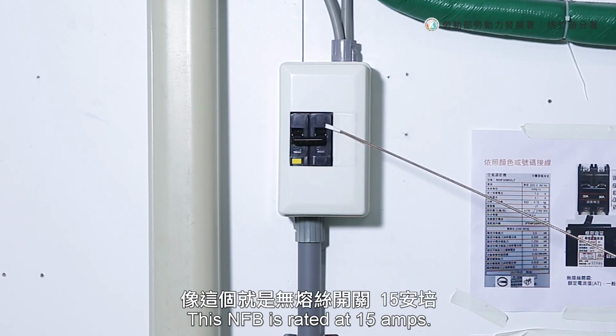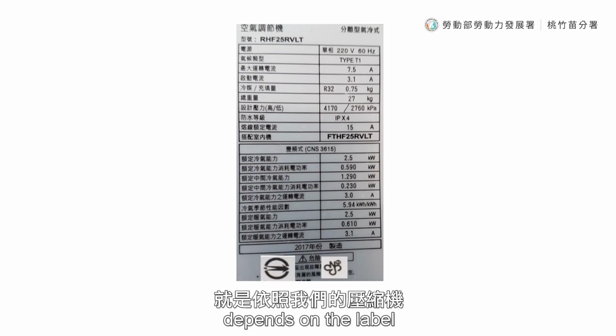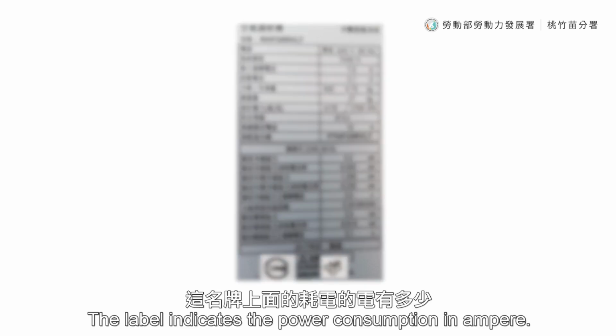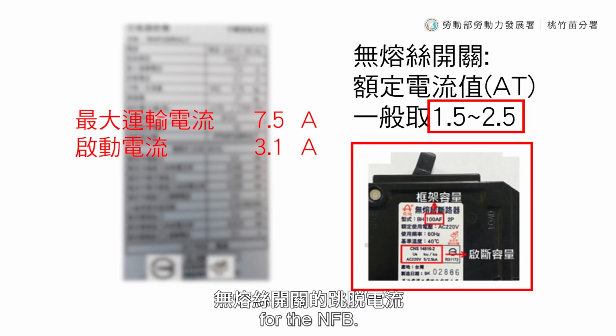This NFB is rated at 15 amps. This is the so-called trip current. How we choose the trip current depends on the label on the compressor. The label indicates the power consumption in amperes. Multiply by 1.5 to 2.5 to determine the trip current for the NFB.